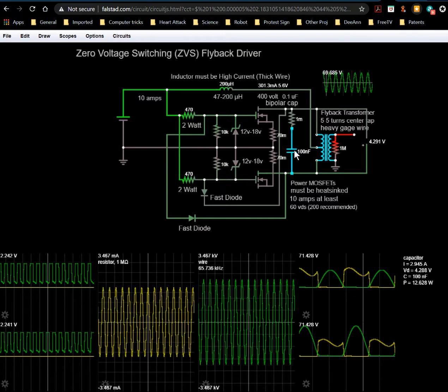That's why you can use an electrolytic capacitor in a power supply, because that never changes. The only time it changes is if you flip this battery upside down and charge it in reverse. Then it changes, and then you blow up your electrolytic capacitor and have a really bad hair day. But generally, it doesn't ever flip the voltage.